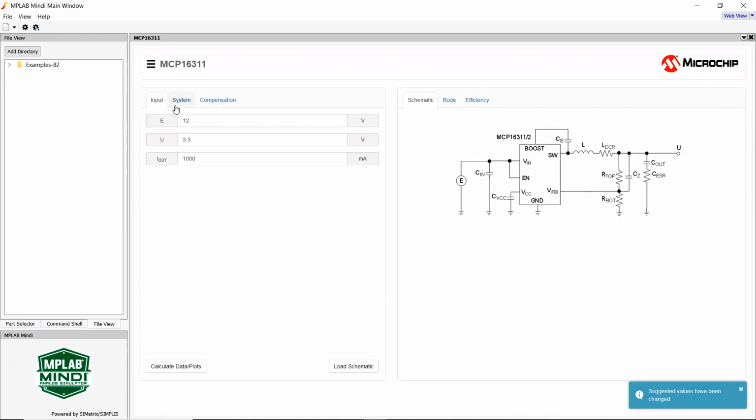So we didn't get a look at that before, but now look. It's 56, but the suggested value is 15. It actually does make sense too. You've reduced the voltages you're working with, so you maybe don't need a big bulky inductor. And this is key because then you're not over designing the system either. So let's change these values to what the suggested ones are, and then we can run another simulation because that's what we like to do. And then we'll see what the results are.